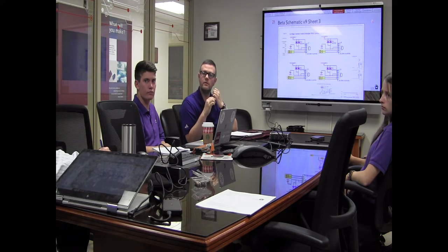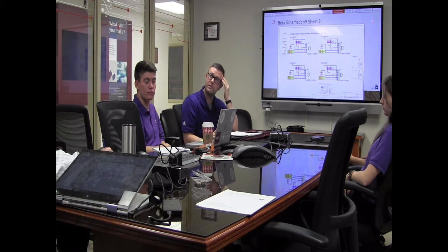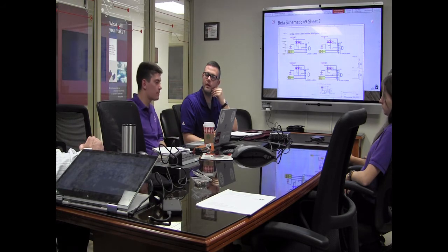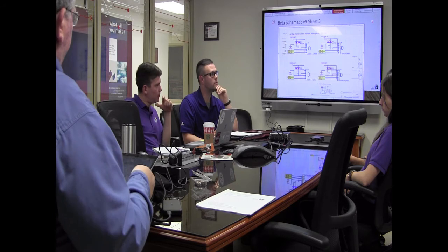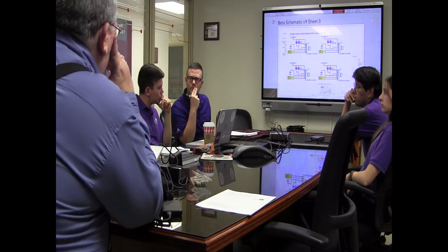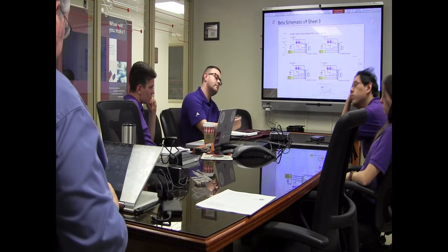But a volt and a half is a lot of drop. Yeah. And you've seen that 1.3 on all of them? Only on the board that we tested. So only on one board, and that was Alpha, because it was on that day that we had that demo. Okay. Have you looked at any of your final boards? Not with a load. Why don't we just check that to do it, if you're still seeing it on final? Okay.